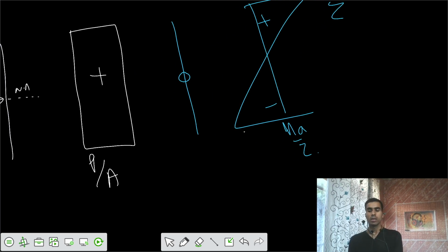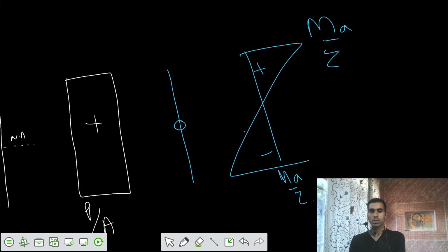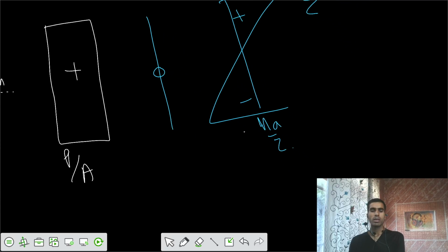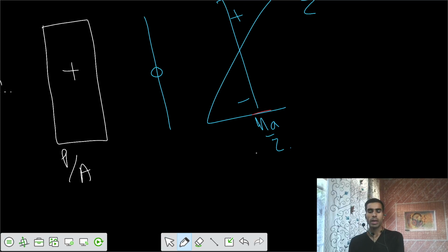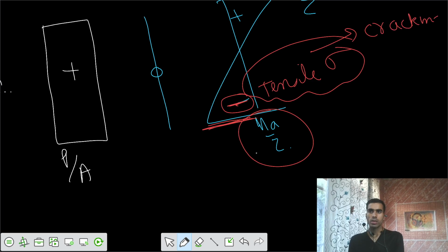Okay, let's take that. I would say that your external bending moments, you can see here, developed some tensile stresses. These are your tensile stresses. So this ensures that cracking of the concrete can appear. Concrete is going to crack because of these stresses.